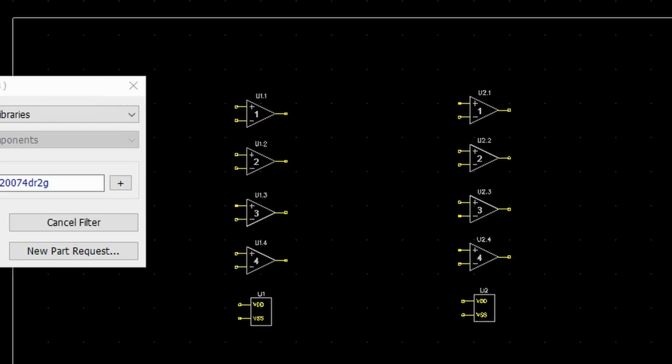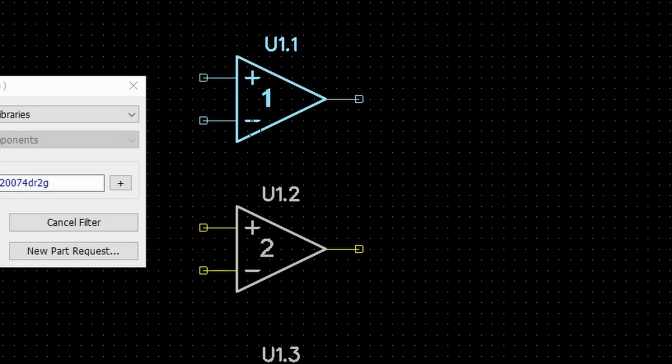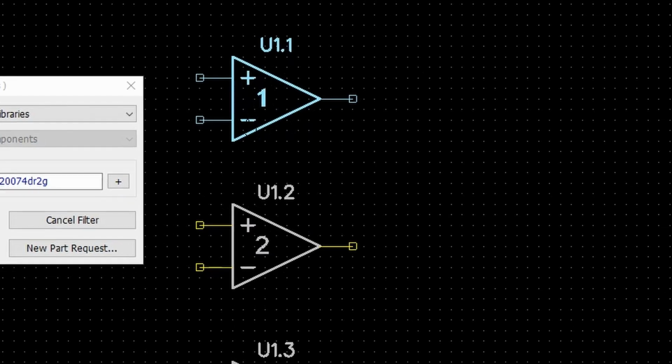Now, in many cases, there are no part numbers or anything placed on this schematic with the part. It's just a symbol and a reference designator. This is because not all library parts come into the schematic with a value specified. You will notice that this is the case with our quad op-amps. So we have to open the properties and assign it a value.